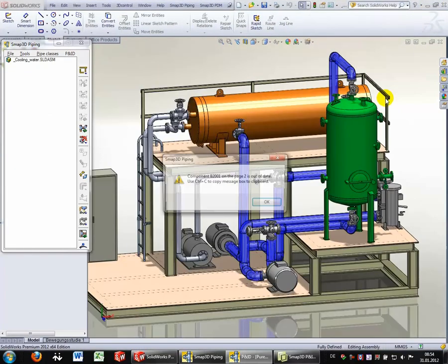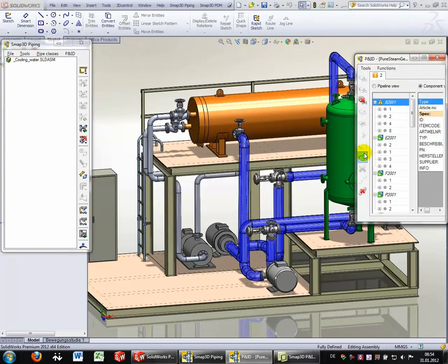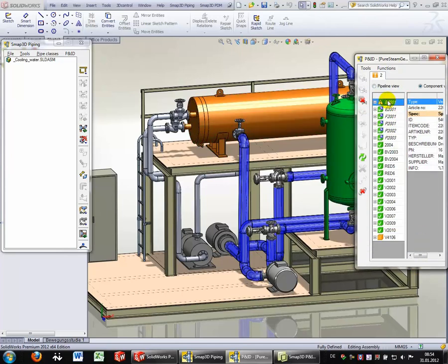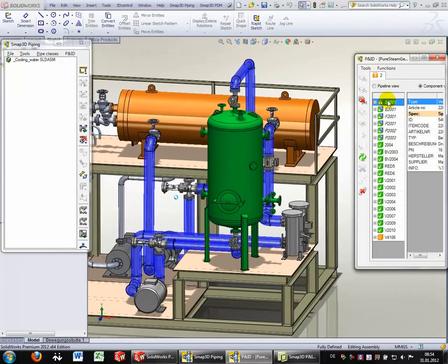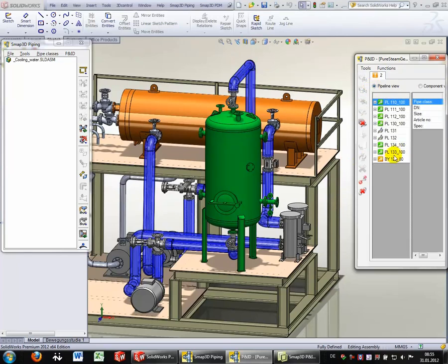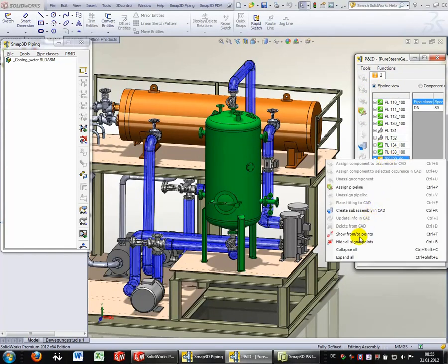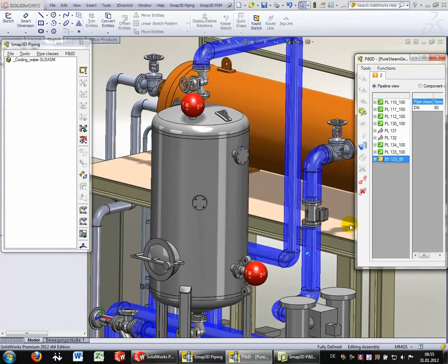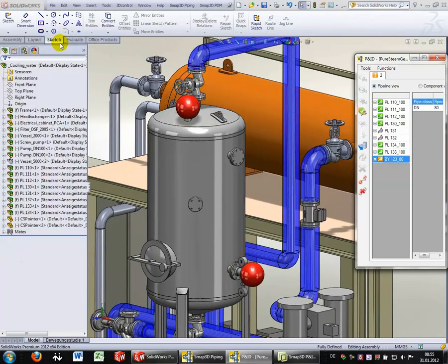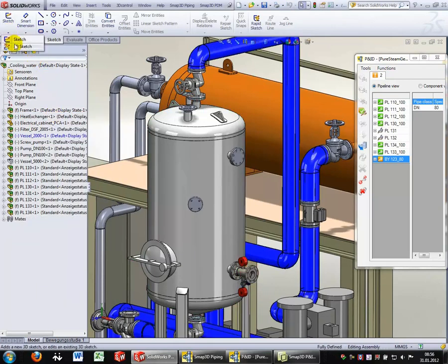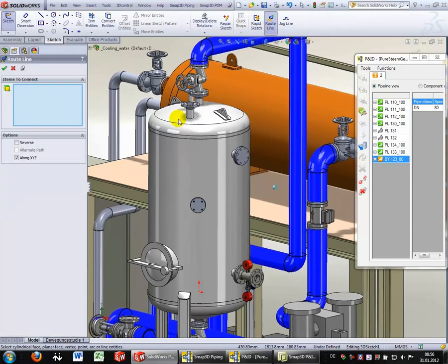After refresh, you see the new and changed content in the Smap3D P&ID to-do list. Some of the out-of-date information you can update with the named functionality. With the transferred information, the user creates the 3D pipeline. The function showFrom2Points helps define the correct connection points on the 3D model. With the native SolidWorks 3D sketch and the included function route line, the pipeline path in 3D is drawn.